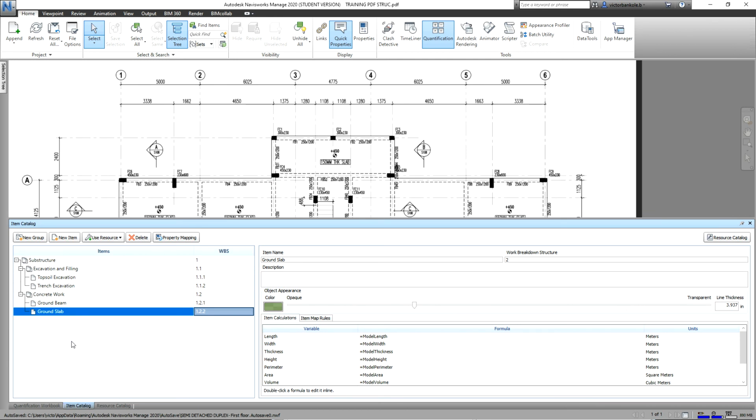Like I often say with Navisworks, the structure, the flow is the same. How you run quantification sessions or exercises for items on your takeoff list follows the same pattern. So if you can take off for trench excavation, you can take off for your concrete. It's the same flow, and it's for 3D model items. You basically click on what you want to quantify, and you do a drag and drop, or you right click and say quantify.